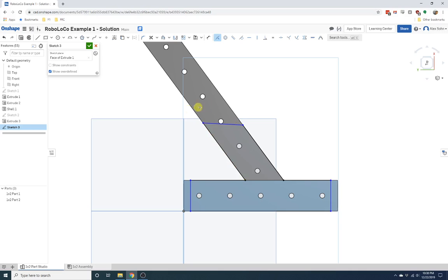All right, so what I'm going to do is make this line perpendicular to this line. All right. And basically, now you see that there are only 3 blue lines left. If you drag this, you can see what I mean by that. Here and here. So I'm going to set a reference. I need to define this length in this direction.